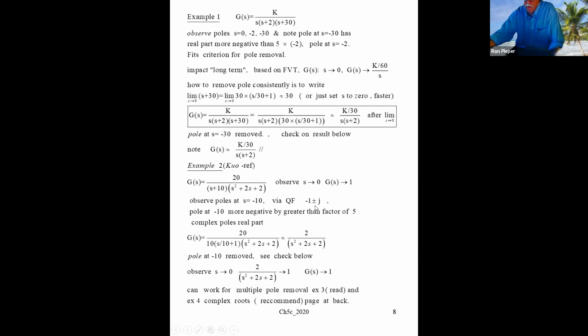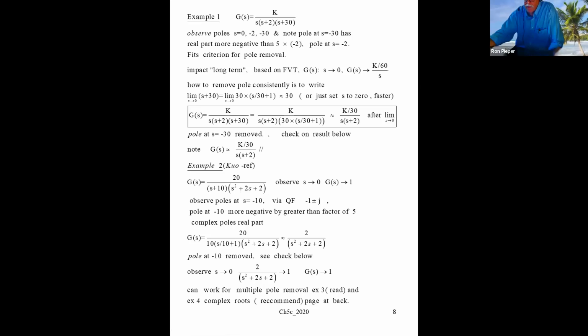It's the real part of the roots that we're doing our comparison with. So since the real part of the root is -1, we can come back and look at our expression again. Which of the poles here looks like you can throw it away? The pole at -10. Yeah, -10. And again, let me remind you, the temptation, which would get you the wrong answer, would be to simply throw that whole thing away, but that 10 carries important information.